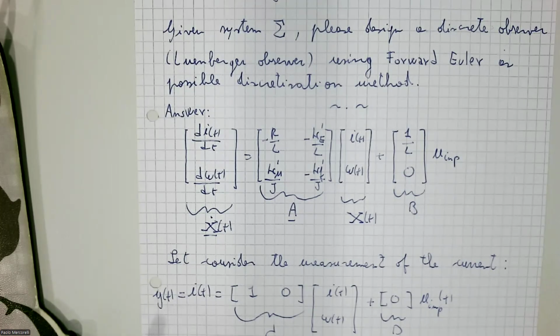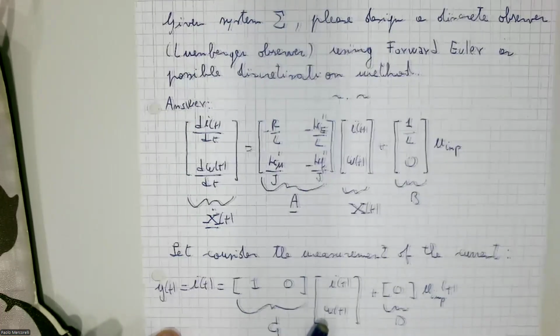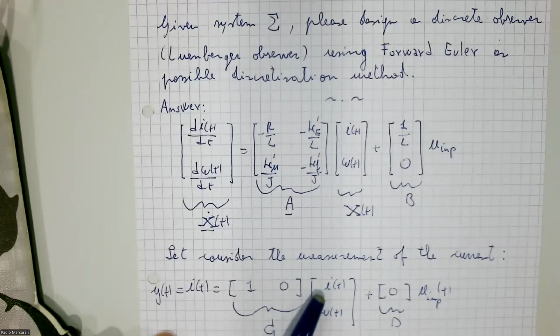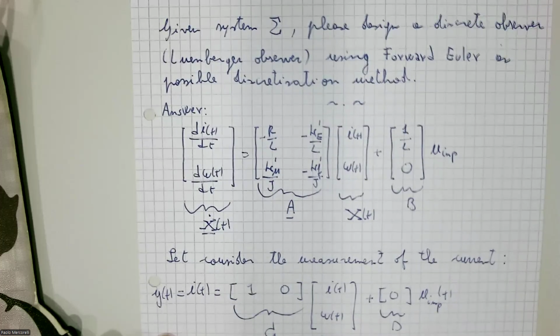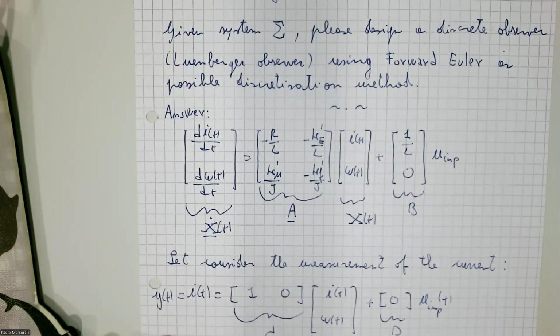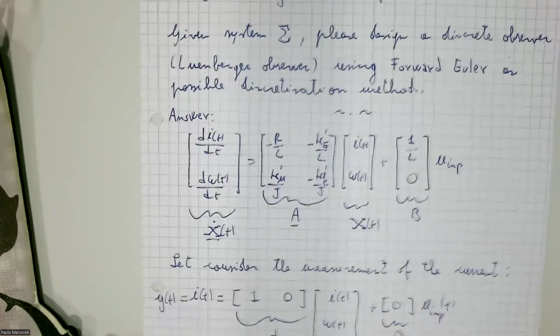I would like to control the omega, but I cannot measure the omega. I can measure just the current. The idea is measuring the current, observe, estimate, let me say observe omega. Before, do you remember, I told you, assuming that I have available current and omega, and measuring current and omega, I predict omega, I control omega using model predictive control.